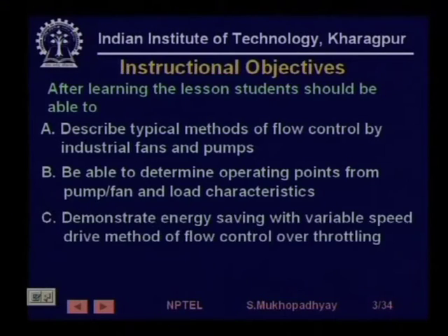So, we are going to see that when you connect a pump or a fan with a so called load, how is the operating point established, what will be the pressure, what will be the flow. It is actually much like establishing an operating point when you connect a battery with a circuit or a load, right. So, we are going to see that, and we will see how we can vary this operating point. See, we have to vary this operating point because we need to vary the flow.